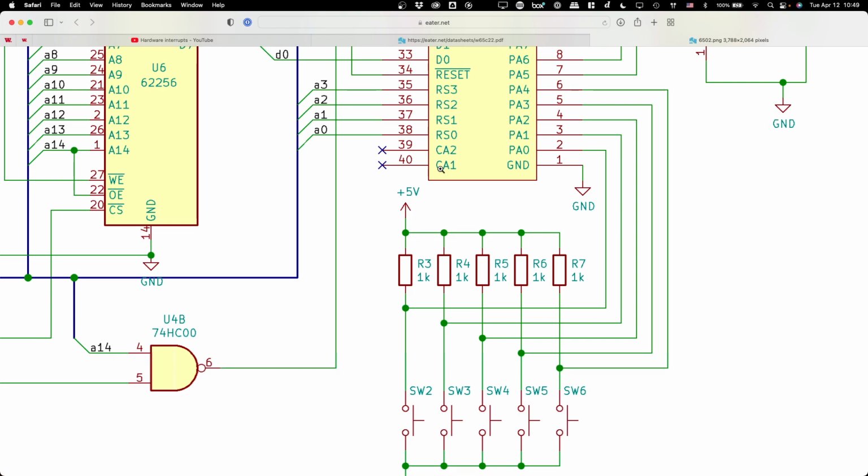Then we read to see which buttons were being pressed at the moment the interrupt was done. We clear the interrupt flags when we read it, and therefore that services the interrupt, and we go back about our merry way.